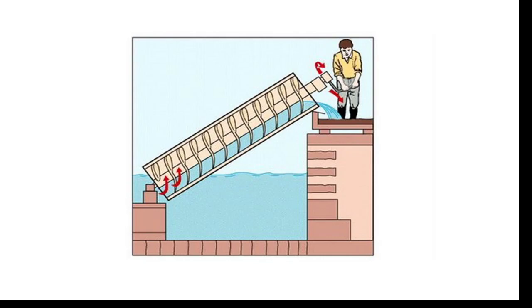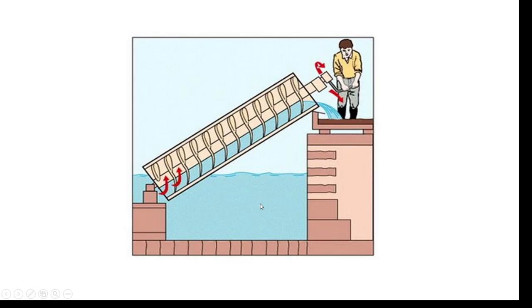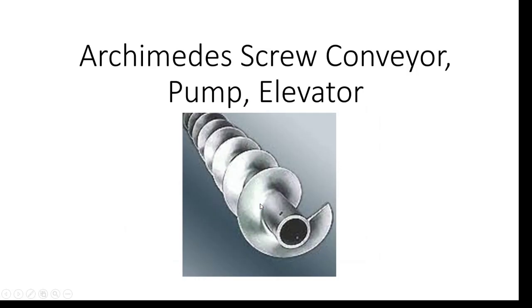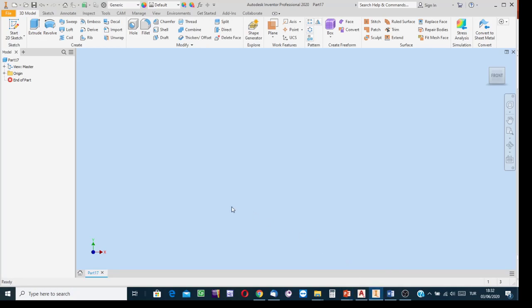The designer considers the strength of the material at the root of the screw, this part. Then, to determine the thickness, considering the shear stress at the root can determine the thickness. In my demonstration, I'm going to say that all of such things have been determined. So, the size of the Archimedes screw has been fixed, and then, knowing the determinate values, we deal with the rest, how the model is created.